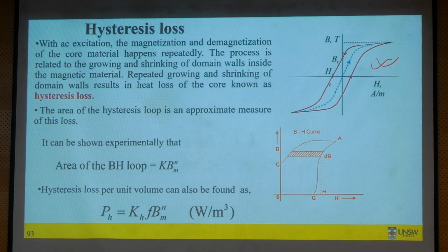So you get the mechanical loss from the dummy rotor, and then you repeat that test with a magnet rotor, do the same thing. The difference between these two losses is your iron loss. Only that way can you measure iron loss. So to separate iron loss, you need a dummy rotor, and usually people do not do it. Why would you make a dummy rotor just to measure the mechanical losses? That's why it's quite difficult to separate iron loss and mechanical loss in a PM machine.